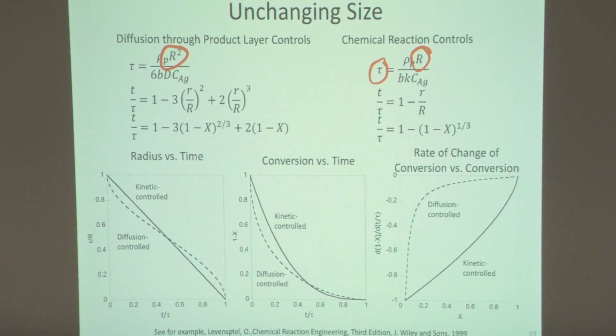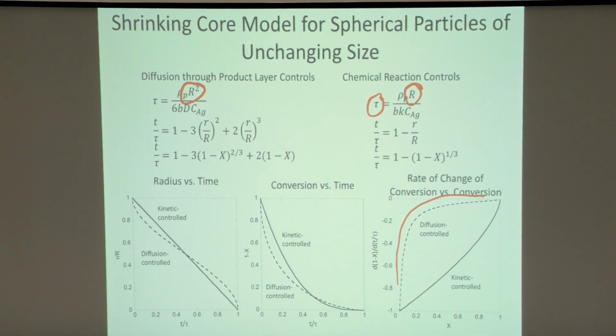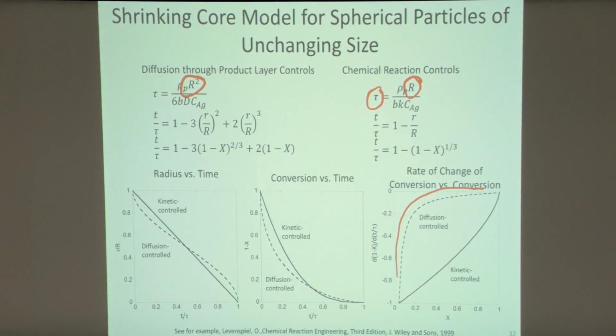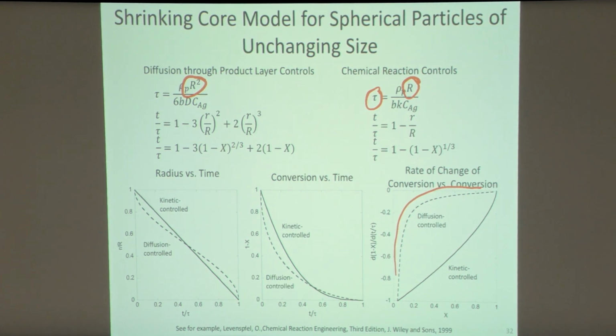Okay, and the line here is for a diffusion-controlled process. And as you would expect, during the first 10 or 20% of conversion of, say, the metal, I'm going to have a very fast conversion rate. And then once 20% of the metal has been consumed, because that oxide layer's gotten so thick, the conversion rate's going to slow down significantly.